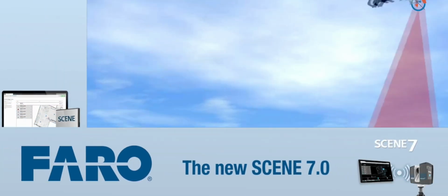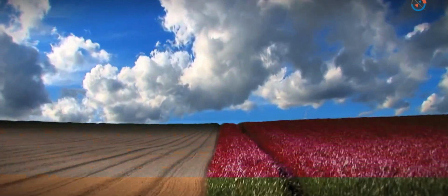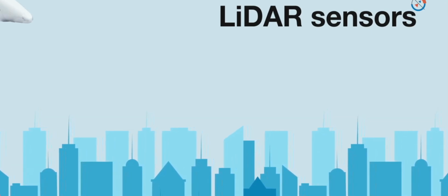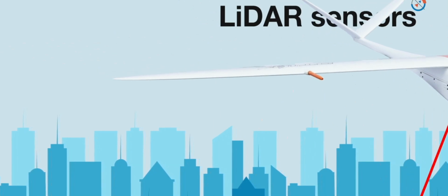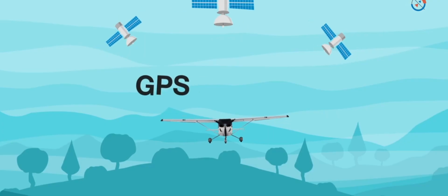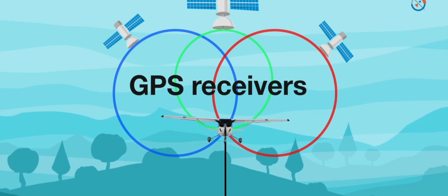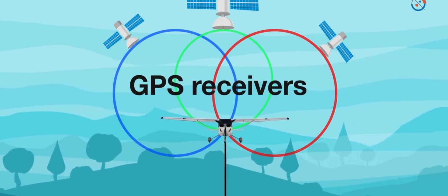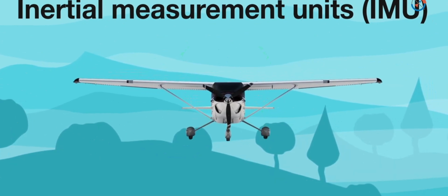An aerial lidar is made up of four elements that work together to detect and range light. As the plane flies, lidar sensors scan the ground from side to side with a pulsed laser beam. The sensor features a detector for sensing the returns from objects. GPS receivers track the airplane's altitude and location. These factors are critical for obtaining correct terrain elevation values. Elevation calculation uses orientation to precisely determine the real position of the pulse on the ground.